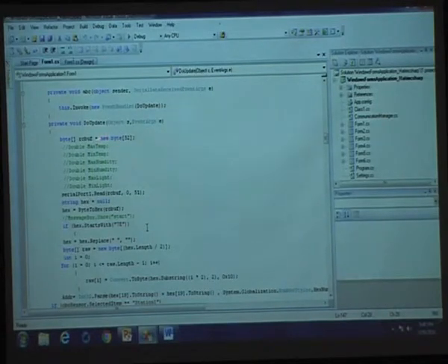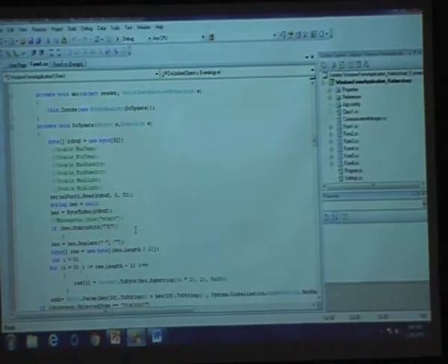Now look at this particular set of statements. There is a temporary variable called RC buffer, which is an array of values. Those values have been collected from the serial port read. The read function is meant for reading the data from your serial port.